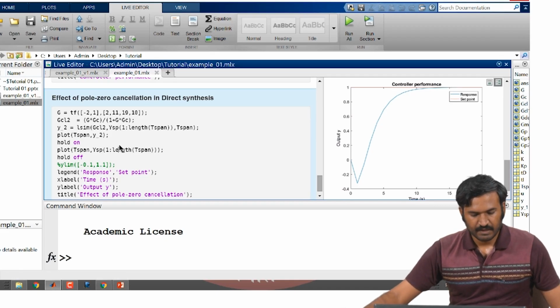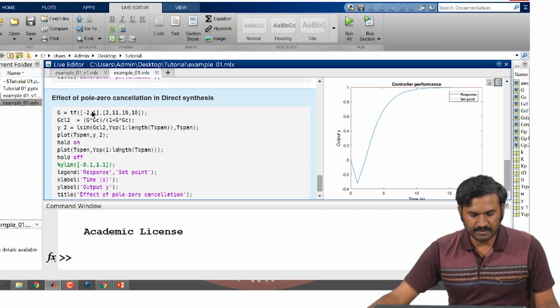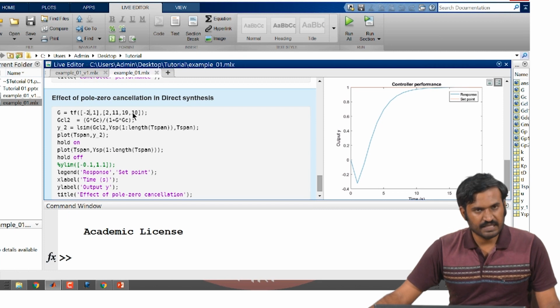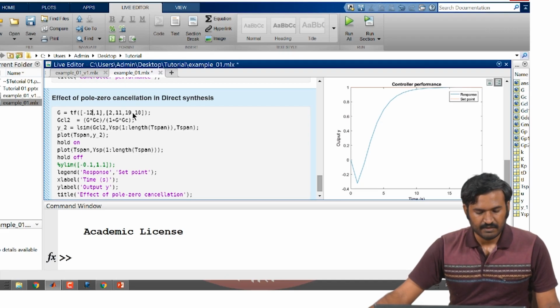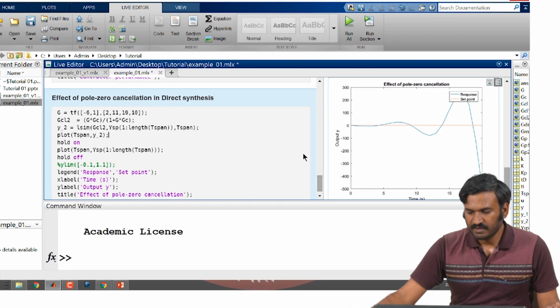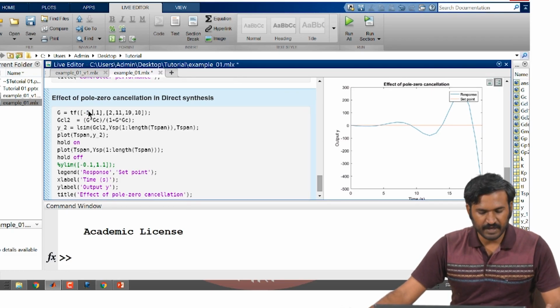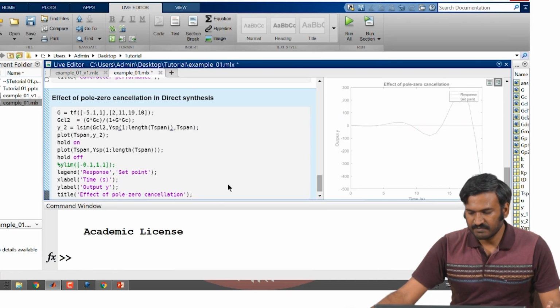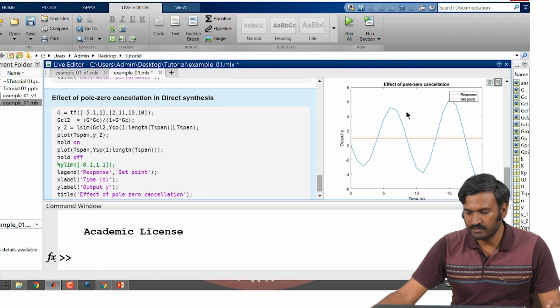example here. So here I have simulated the same controller configuration and used the same model here. Suppose let us assume this to be 12, or let us assume it to be 6 and then run this code. So as you can see, the system starts to become unstable here. Even if it is something like 5.1, you will find that the system starts to become unstable. So the magnitude of the oscillation keeps on increasing.